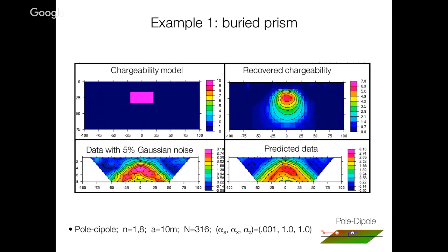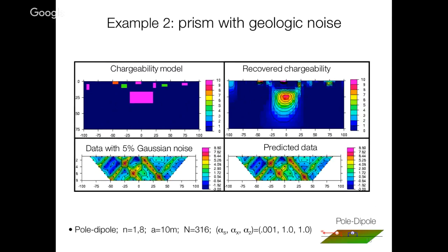So now let's look at our inversion examples for a single prism. Here's your pseudosection. There's the recovered chargeability. So that's great, right? We've got this guy completely localized. And here, where we had mucked data, we recover this. So we not only have the body, but again, we've got some manifestation. Like here's some of those chargeable bodies. So they might just be surface graphites or clays.